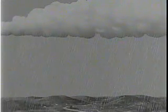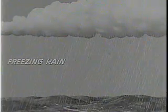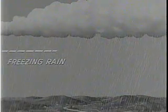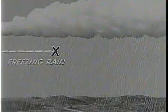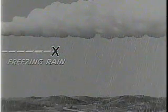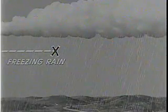As we have seen, areas of freezing rain are the most hazardous for structural icing. This pilot is flying through rain at freezing temperatures. If he continues at this level, the aircraft will quickly accumulate a dangerous amount of ice. In such a situation, you must immediately find warmer air with temperatures above freezing, or turn back.